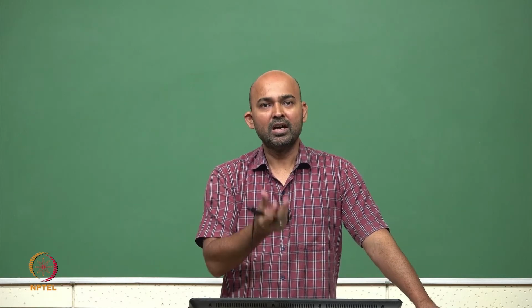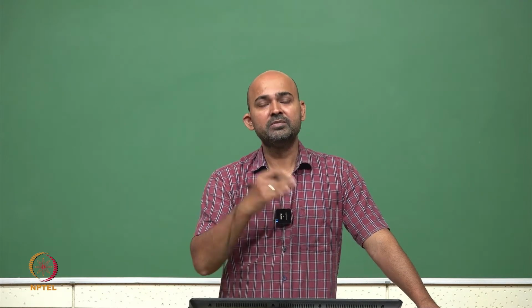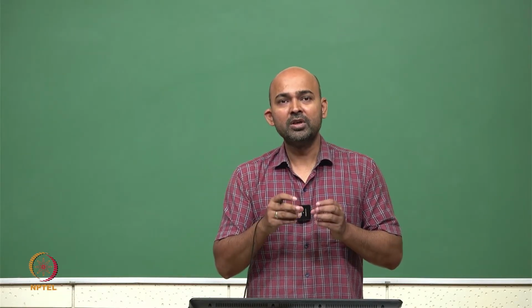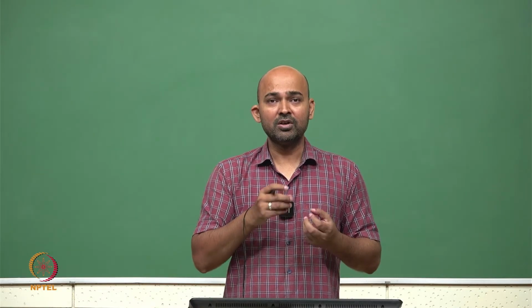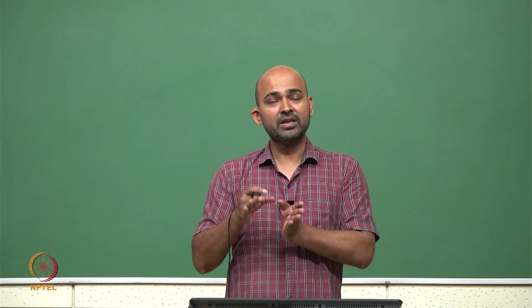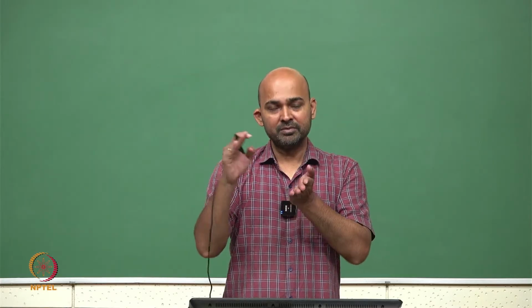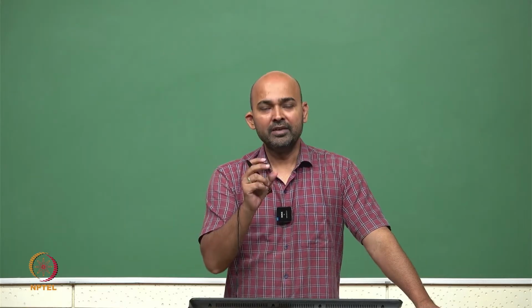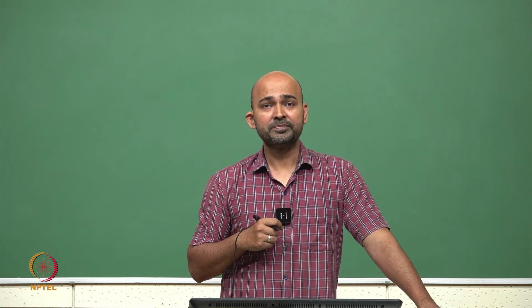We can put that on the RF substrate, which can act like an antenna and transmit and receive the RF waves. At low frequencies it is not possible to put the antenna on the PCB or in a handheld device because the size of the antenna is very big. However, if we go to RF frequencies where the frequency is very high, the wavelength of these waves becomes smaller, so the size of the antenna becomes smaller, and we can put this antenna on the PCB or the device itself.